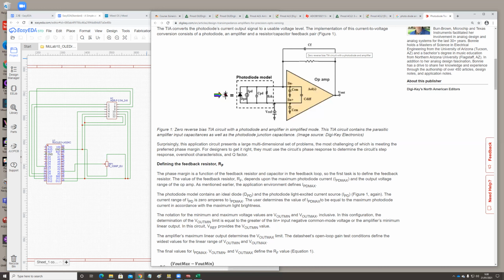So it is nanoseconds of duration of the pulses there of the light, and then this is a really small capacitor in here. But if you try to avoid the 100 Hertz or 50 Hertz flickering of the lamps, you put a large capacitor here, and then you still get a stable output from here. So that's how a photodiode circuit is working. A photodiode in here gives a small current, you measure the current flowing through a resistor, and then you measure what is the voltage on the other side.